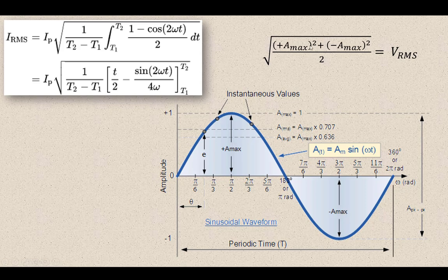Now I can add two positive numbers together, this one squared and this negative one squared, divided by 2. And I will now take the square root of that to undo what I did with the square, to give me volts RMS. I'm taking the root of the mean, the average, of the squares. Root, mean, squares.